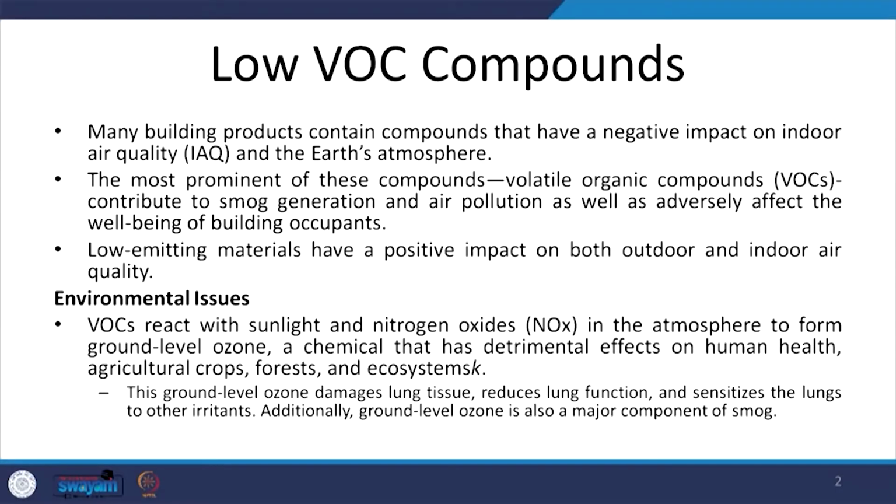to respiratory problems. So for any building to be a sustainable building, a green building, VOC compounds should be limited, so that not only is the environment good, but it is good for the human beings, the building's occupants. So the intent is to reduce the VOC compounds in the building interior by selecting the materials carefully. Certain materials emit more VOC compounds, while others emit less. So we have to reduce the VOC compounds by selecting appropriate material.